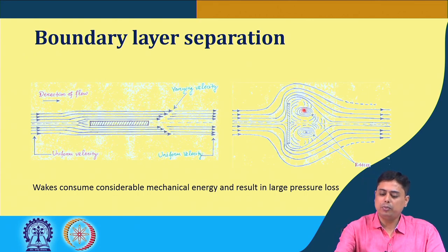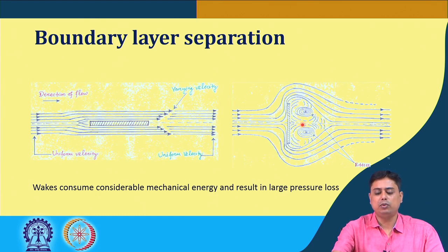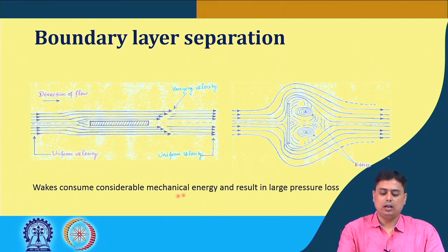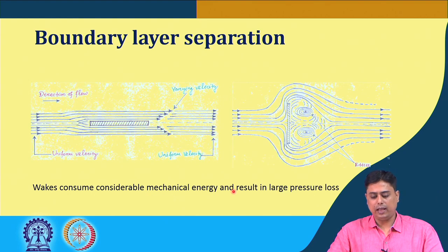This formation of wake happens due to boundary layer separation, because the flow cannot abruptly come to this point and it flows with the momentum of the flow. In such a scenario, the eddies or the wake form, and that leads to considerable mechanical energy loss and pressure loss.